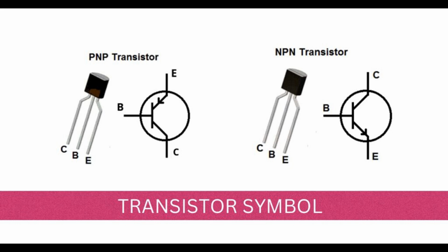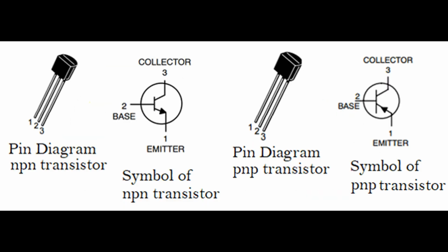Darlington transistors are commonly used in applications that require high current amplification, such as power output stages of audio amplifiers, motor control circuits, relay driver circuits, and high current switching applications. It's worth noting that the Darlington configuration introduces a higher voltage drop between the collector and emitter compared to a single transistor due to the combined voltage drops of the two transistors. Therefore, it is important to consider the power dissipation and voltage requirements when using Darlington transistors.